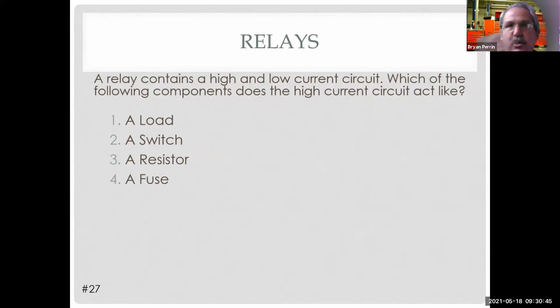That's what allows us, because a relay pulls about 50 milliamps, not very much. So it's not going to adversely affect a circuit I've attached it to, because it just doesn't pull that much current. But I can switch 30 amps with 50 milliamps. That's huge. So it really allows me to use a very low current circuit to switch a high current circuit. And they have 50 amp relays also. So you can switch a lot of current with a very small amount of current.